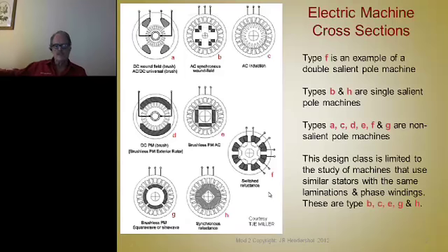But you'll notice that this little chronology starts with the commutated DC motor. Here are your field windings in the stator, and then your armature windings on the rotor. And those are the commutator bars there, and these represent the brushes. So each one of these coils is one pole, and there's a second pole. That means the coils are going to be wound across 180 degrees apart. It'll be a coil there and a coil there, and then pairs of those coils wrapped, stepped all the way around in a lapped fashion.